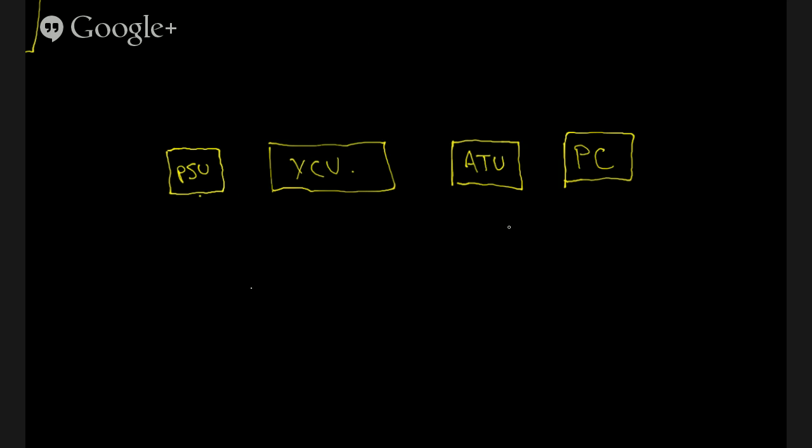Ideally, we would want all of these to share a common point ground. These are all connected to earth ground, which is simply a long rod driven into the ground to provide good conductivity with the soil.